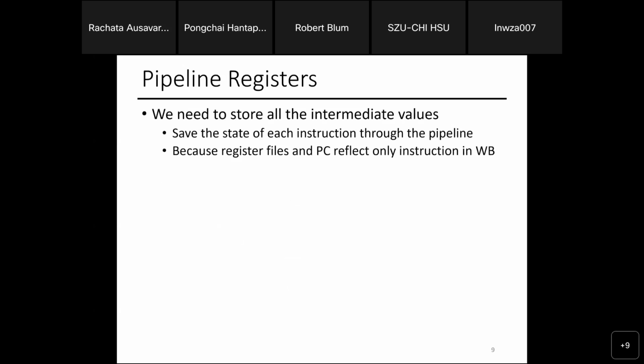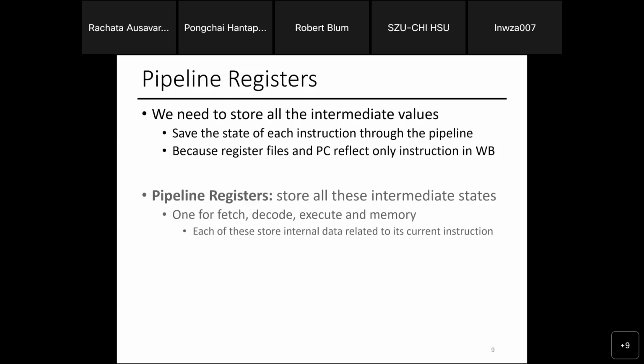It's a buffering area implemented in almost a similar fashion to your register. Sometimes cheaper, to be honest, because we can make it cheaper. But the idea is I can buffer intermediate values between the steps. Usually there'll be one for fetch, one for decode, one for execute, and one for memory. In a deep pipeline design, like your laptop, which has, I would tell you, more than 30 stages. Yeah, that's how deep the pipeline is for your laptop.